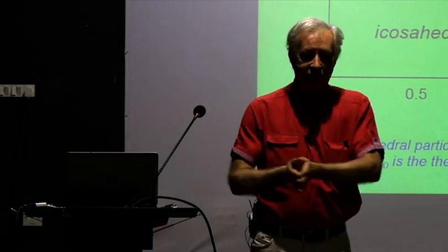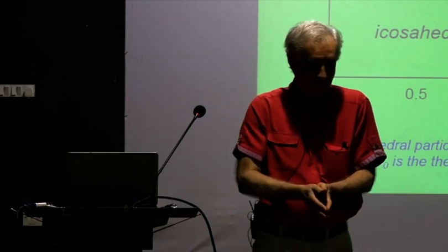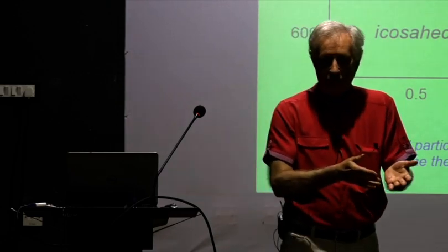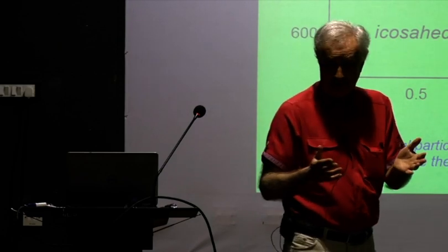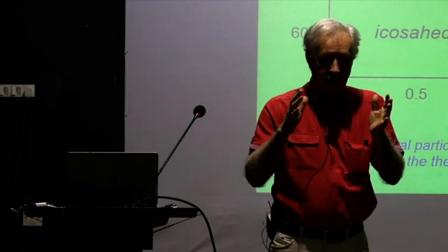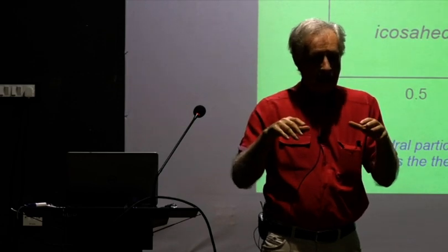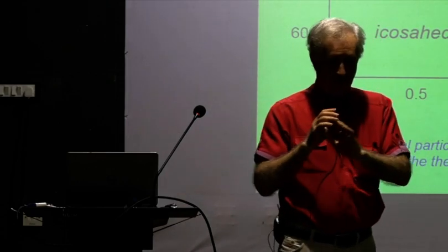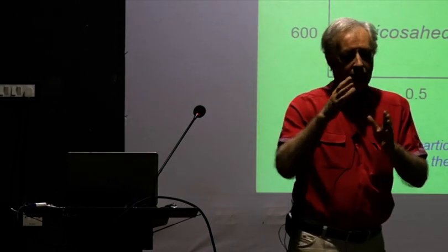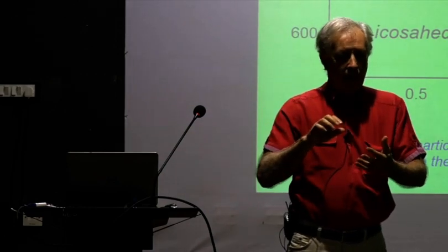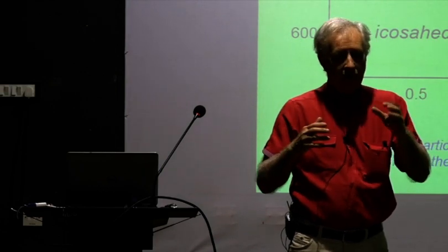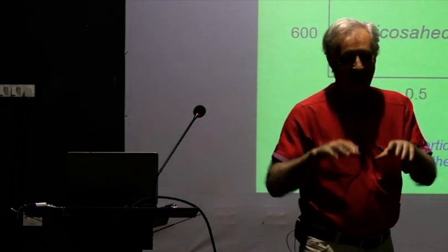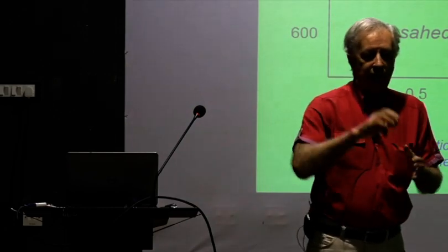We went back to our experiences in magnetism and how we could use them. In fact, we went back to FCC iron, to the anti-invar problem. FCC iron is cubic, and it is possible to incorporate nitrogen into the structure. If you put nitrogen into the middle, you have FCC iron plus nitrogen, which is actually an antiperovskite, Fe3FeN, in a sense. It's like Mn3GaC, but Fe3FeN.